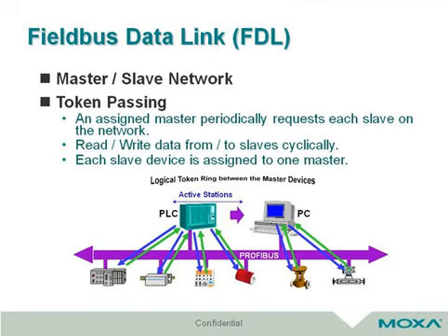Generally, the master device will generate a write or read command to write data to a PROFIBUS slave or read data from it. Since the PROFIBUS application allows multiple masters, which master is decided to be the one to talk? Easy. There is the token, which will be passed among the masters. The master which has the token on hand can talk.